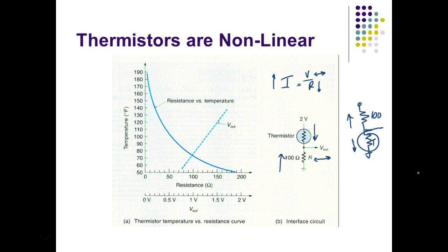Do you want your voltage to go down when your temperature goes up, or do you want your voltage to go up when the temperature goes down? And this is one reason an NTC, negative temperature coefficient, would work in both situations, because it depends on which direction I put the thermistor at, right? You understand? Either the top of the fixed resistor or the bottom of the fixed resistor.